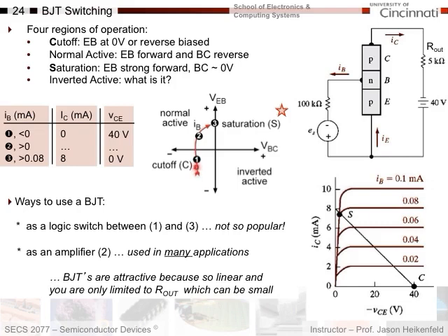So if you look at this, then why am I over here? So why is the curve over here? Well, look at VBC, okay? I've got 40 volts applied across here. If voltage sums to 0 on a loop, if this is plus 40, then I should have minus 40 here across VBC, and this is basically showing me my minus 40 volts here, okay? And so no matter if I keep reverse biasing this more and more, it doesn't matter, the voltage drop will be across here for this loop here.